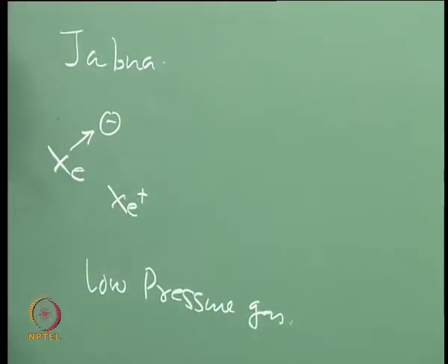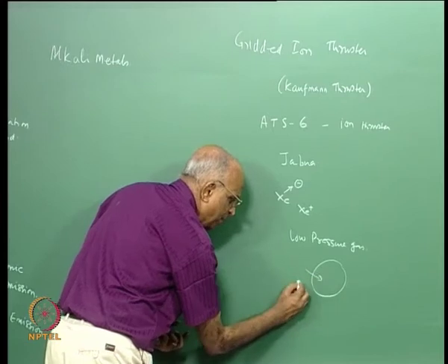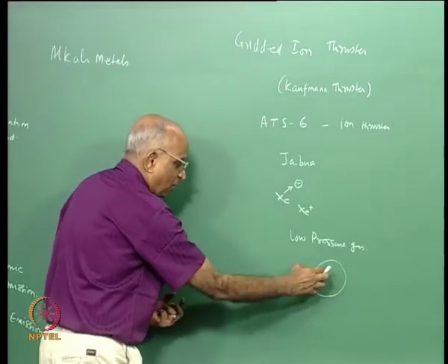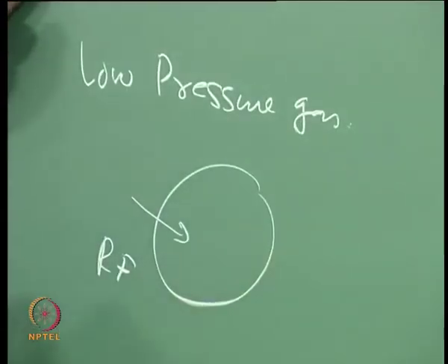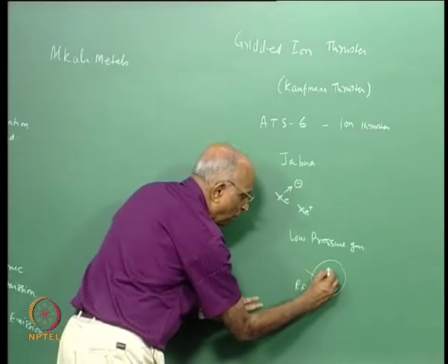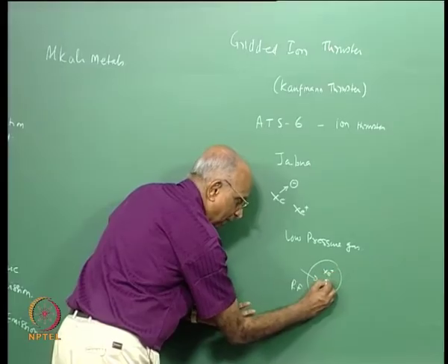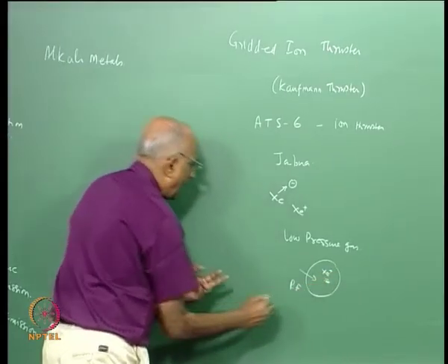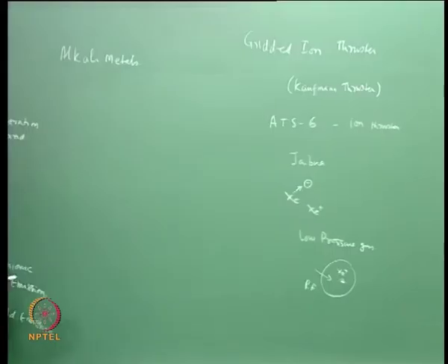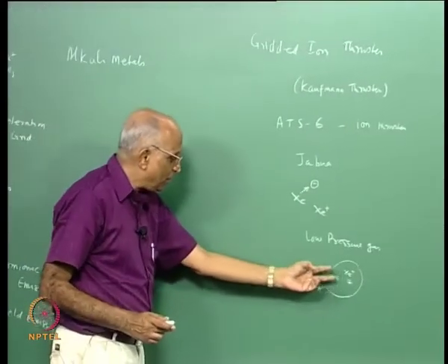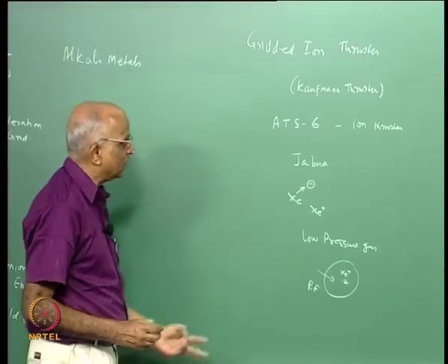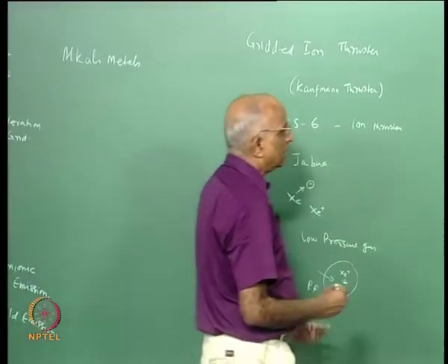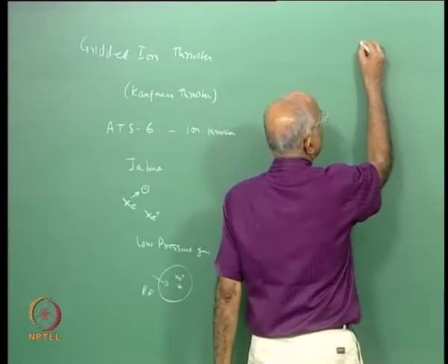I have a volume of gas, I put radio frequency into it, I sort of excite the gas and heat it, and in that case when I heat it, gases like xenon tend to form maybe positive ions and negative electrons, and I use the same attractive forces and do this. In other words, I use radio frequencies also to generate positive charges, and if I use radio frequency, well, the thruster is known as a radio frequency ion thruster.